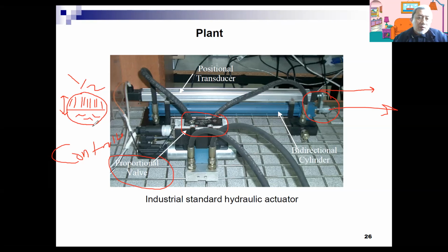But if the valve of the black pipe here is open only 25% or maybe 10%, and the rest is blocked, the flow inside the pipe will be slower due to the low pressure. So you can see that the piston of the cylinder slows down.